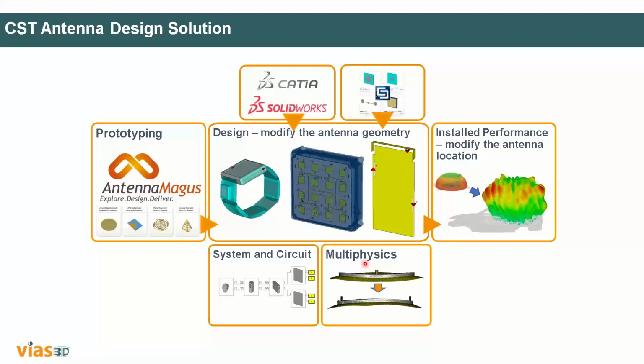And finally, the multiphysics. Almost 90% of the time, none of us bothers about what will happen to the antenna when it is working continuously. If you consider a high-power antenna, it is continuously working, it will generate heat, and this temperature can create shape deformation in the antenna, and that will result in a different pattern than the one we intended.